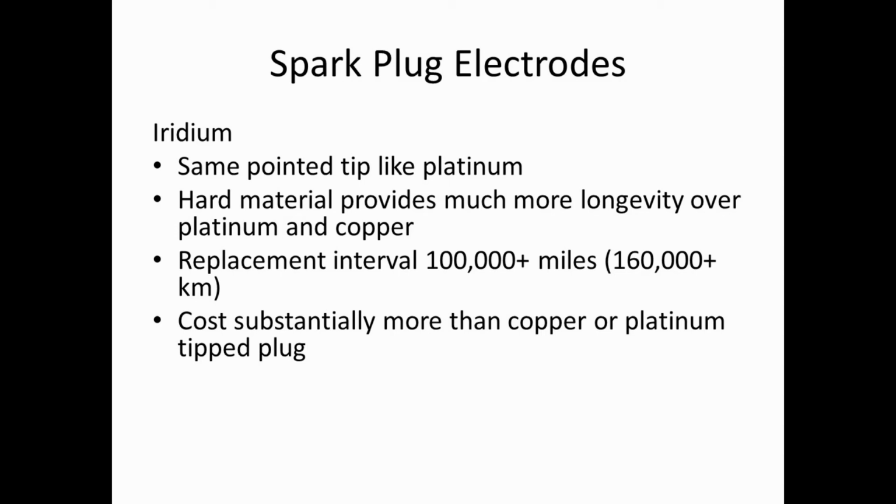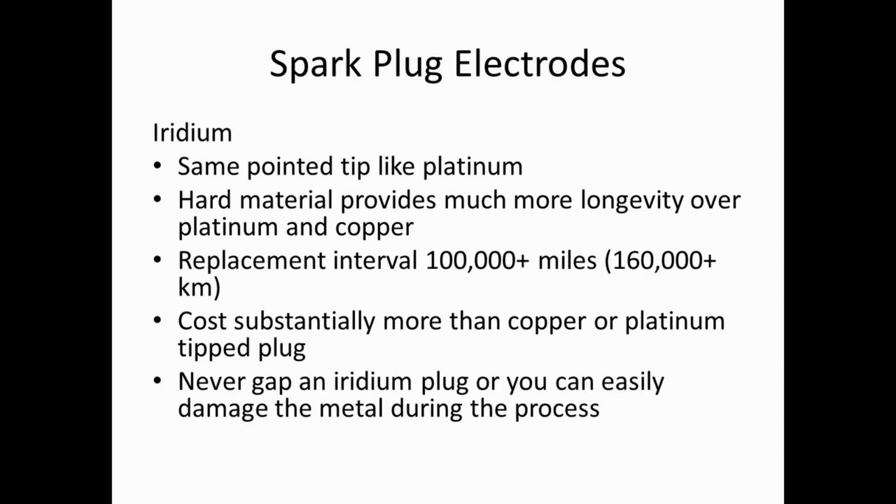So where a copper plug is $3 to $5 and a platinum plug is anywhere from $5 to $7, an iridium plug's usually about $12 to $15 each. So if you're putting a bunch of those iridium plugs in, that gets to be a very costly repair. Also, you never ever gap an iridium spark plug because the metal is easily damaged during the process. So just leave the gap alone if you have an iridium plug.